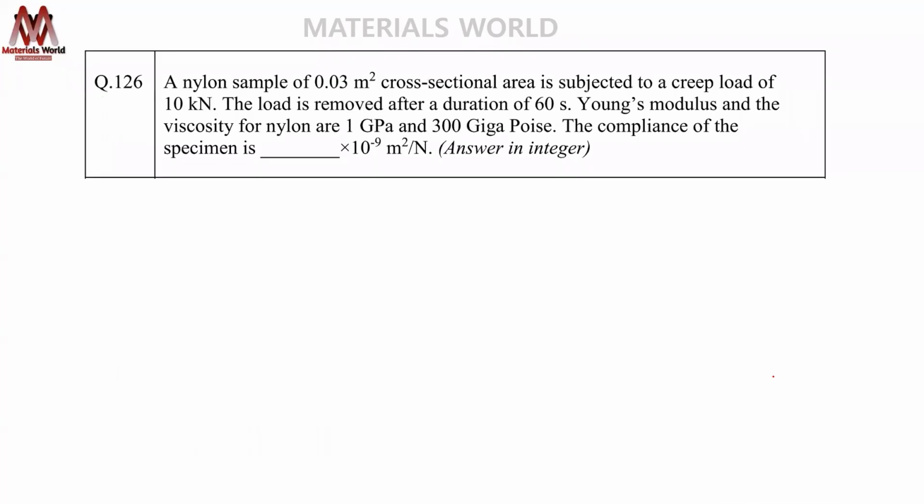Now, A and D. This is a very typical question. Here, actually, it should be mentioned which model you should use to estimate the compliance. Like you can use the Voigt model, Voigt element. Definitely, you should not use the Maxwell element for compliance or for a creep experiment, because the Maxwell element tells you something like this. With time, how strain is changing, something like this.